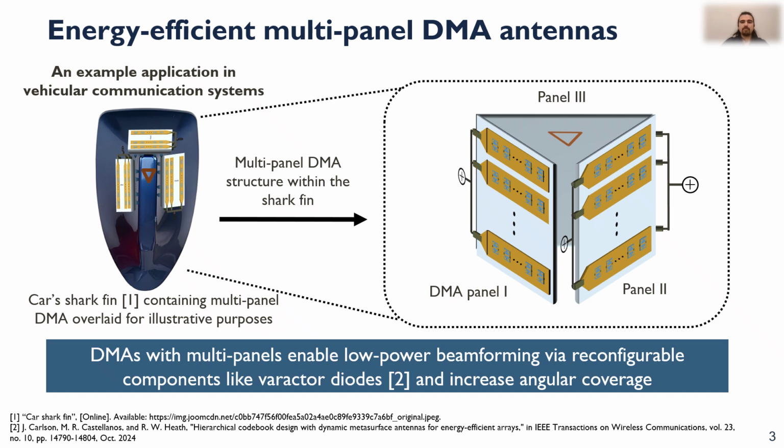Here, however, the DMA beamforming weights follow a constraint which is called the Lorentzian constraint. The constraint couples the DMA beamforming weight amplitude together with the phase. So it complicates the beamforming solution as well as limits the angular beamforming coverage.